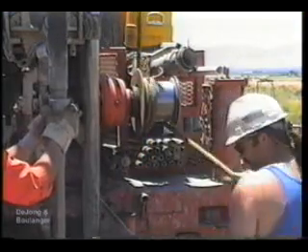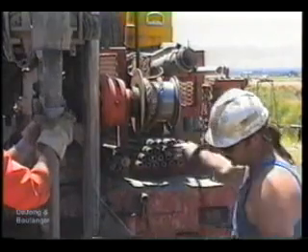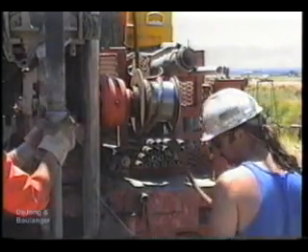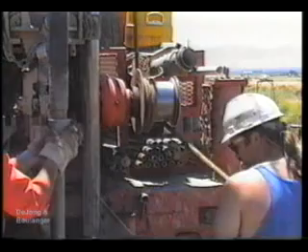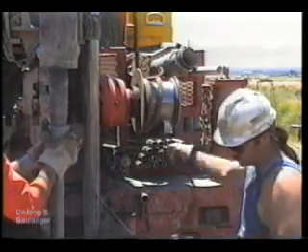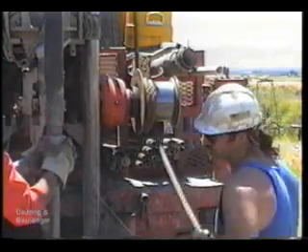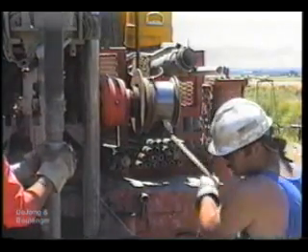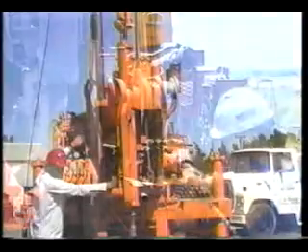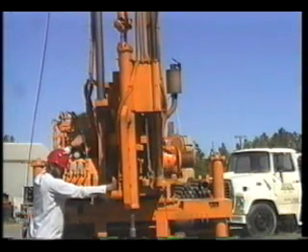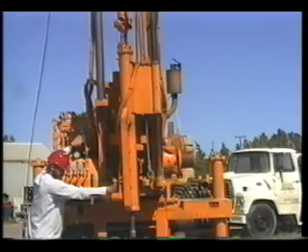The driller lifts the drop hammer by pulling on a rope that is looped around a rotating drum or cathead. By pulling the rope, the operator uses the friction between the rope and the cathead to pull the hammer up. The hammer is dropped by releasing the rope, thus reducing friction between the rope and the cathead. The trip hammer performs the same function, only mechanically.